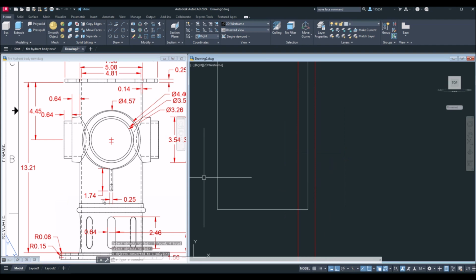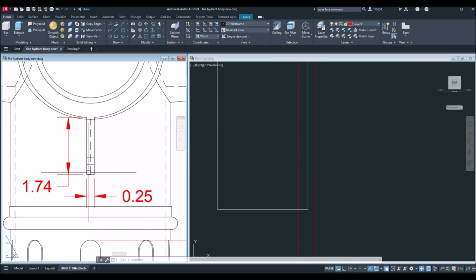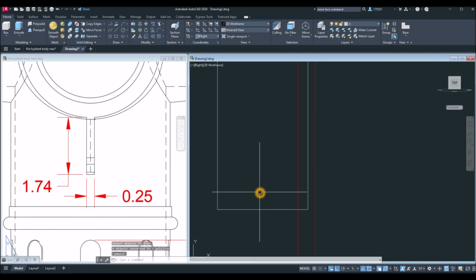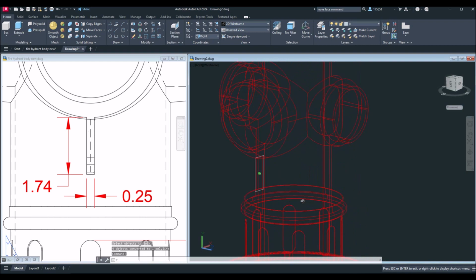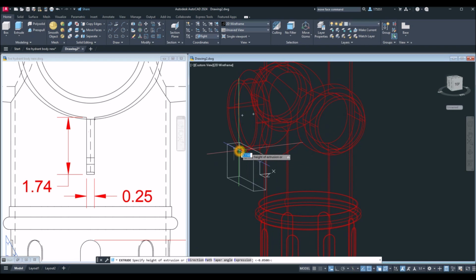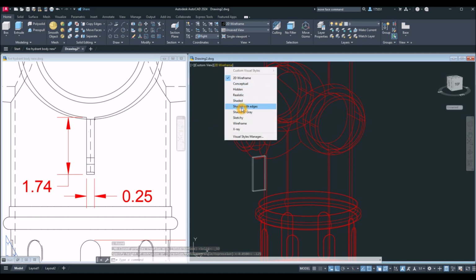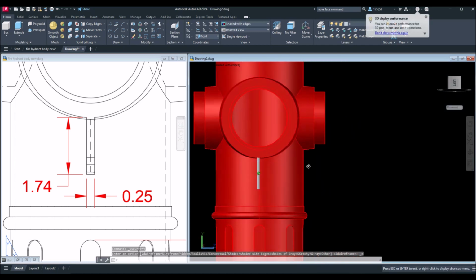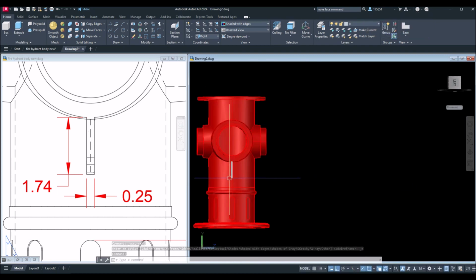Now I'm going to extrude this object halfway, so I could center this thingy here. So 0.25, 0.125 is half. So just hold down the shift key and the wheel of your mouse and select the object you want to extrude. And extrude it for 0.125, which is half of 0.25. Just gonna change this to shaded with edges. And so I extruded it to that direction.